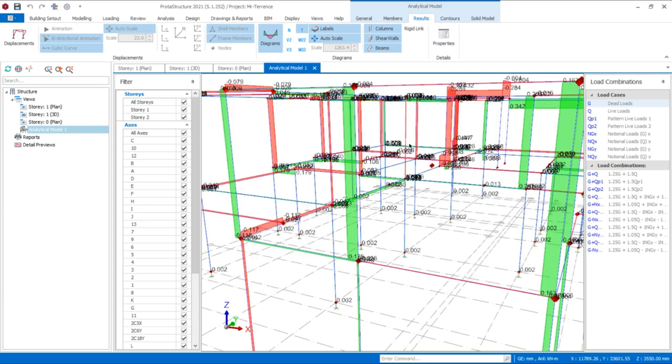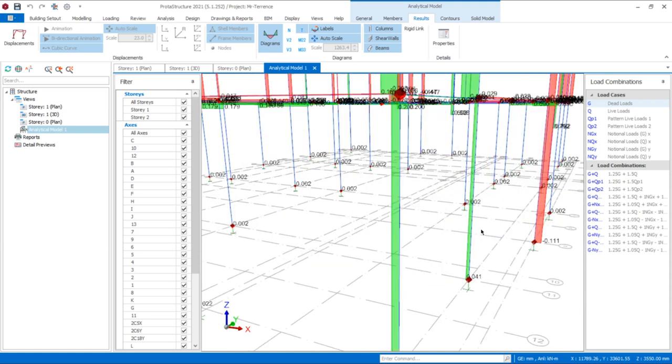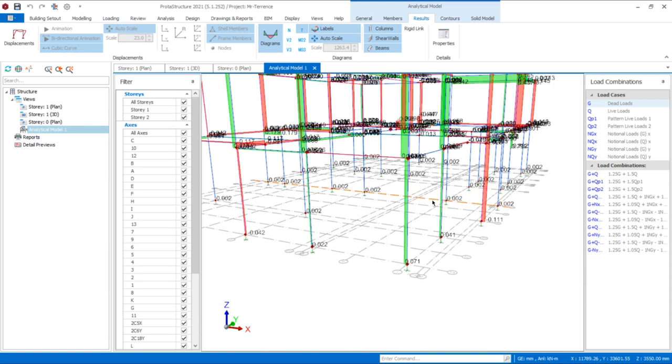Torsion means twisting. You can just imagine holding one end of a towel while twisting the other one. That is torsion. In buildings, torsion commonly occurs in edge beams supporting cantilever slabs, curved beams, or structures with irregular layout. So in this project, the torsion values are relatively small, and that's a good sign because it suggests the loads are being transferred without excessive twisting. Then we have M22.